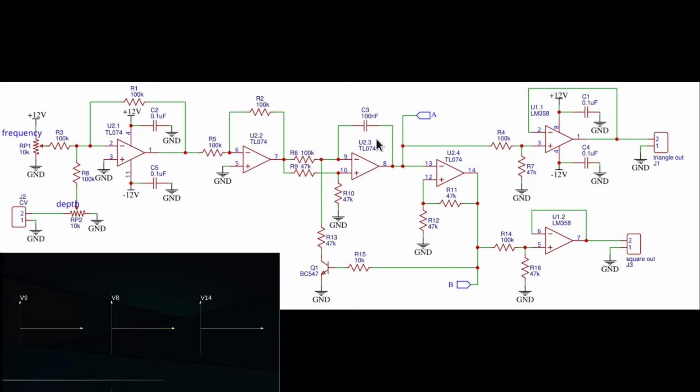This makes the voltage at pin 9 increase linearly, while voltage at pin 8 decreases linearly, at the same pace, of course. The voltage at pin 14 is currently a steady low, since voltage at pin 13 is more negative than pin 12.